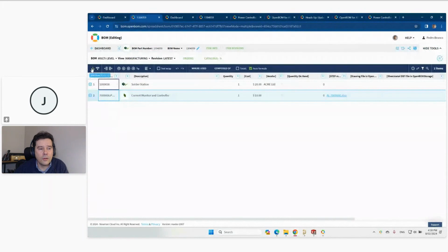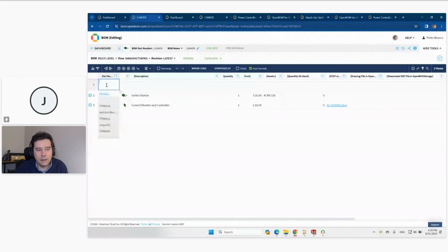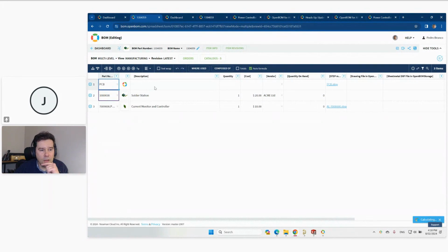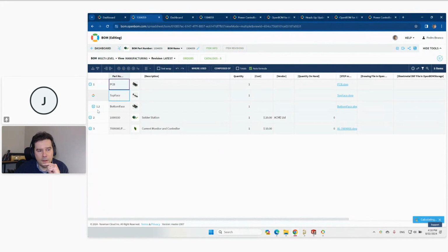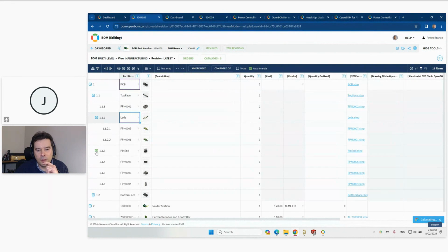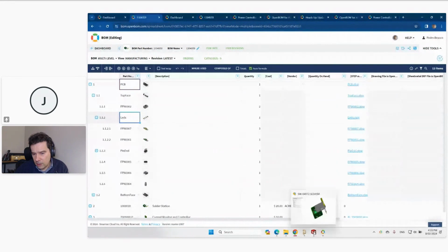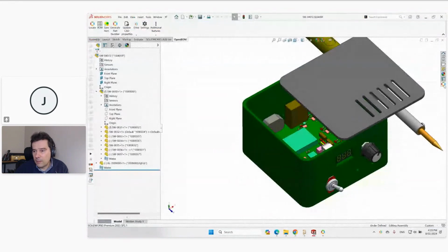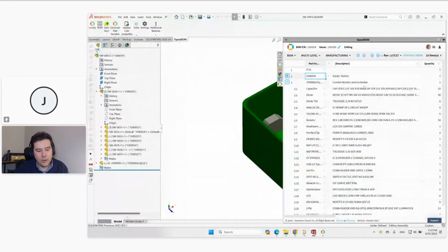So you can just add a new item and type the part number, for example, and you have the Fusion structure. That's what you got from Fusion with all levels. And this is the product structure. You always work on the complete structure everywhere. So even if you go back to SolidWorks and you see now the updated bill of material, notice that the full product structure is updated.